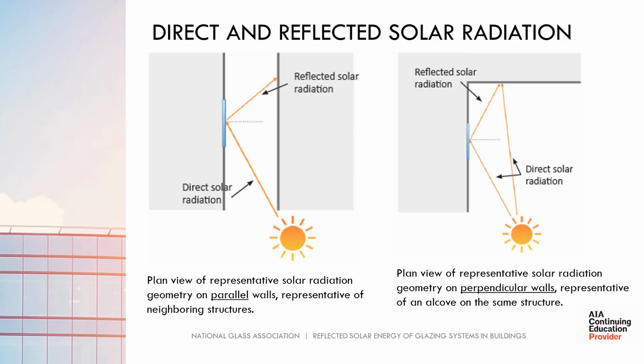On smooth surfaces such as window glass, accumulated snow, and swimming pools, the reflection is direct and its path is determined by the angle between the line normal to the glass surface and the Earth-Sun line, which is a combination of the solar azimuth and solar altitude.